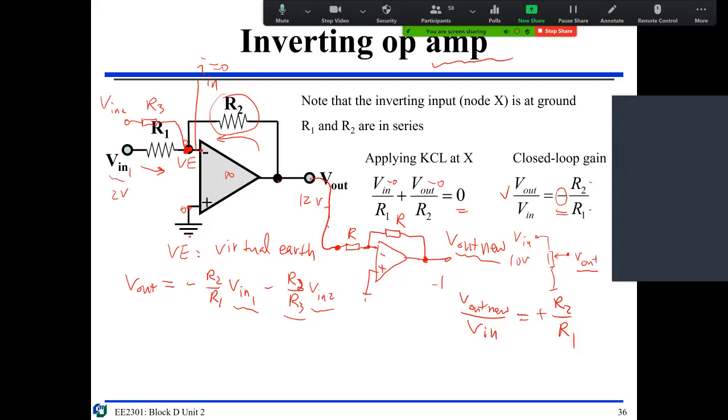So you have two signals, you want to add them together. You cannot simply solder them together and then expect it will add together. That's totally wrong. Don't make that kind of low-level error. People will laugh at you and also me and say, how come? You have to use this op amp to be able to add those two signals together, like this.